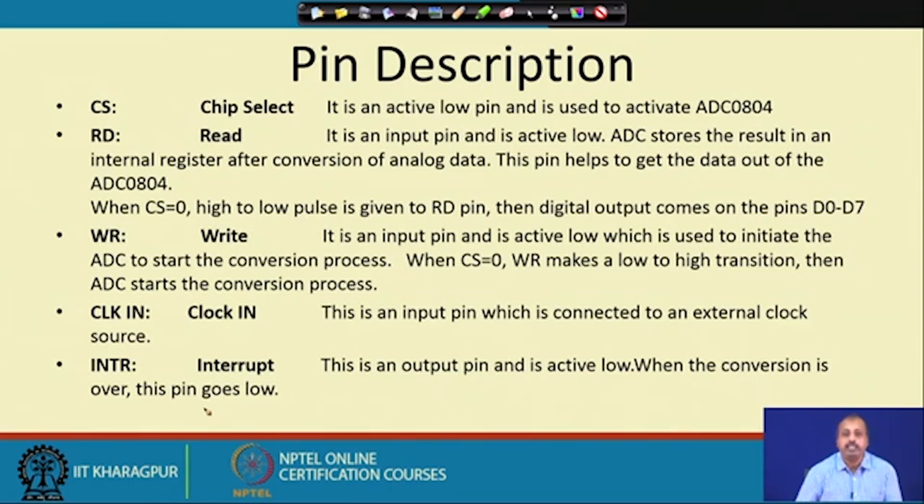Accordingly, this particular line may be connected, say for the 8051, to the INT0 or INT1 pin, and accordingly it will jump to the corresponding ISR. In that ISR, we can activate this read bar line, and accordingly we can get the content of this converted value.